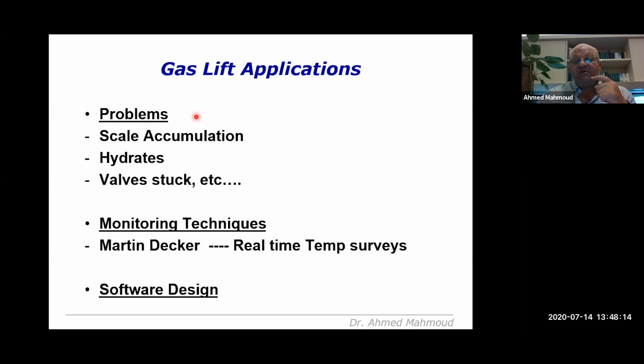And the main problem with gas lift applications is scale accumulation. And scale is very prone to accumulate. It really likes the pockets, it really likes the mandrels, it really likes the springs inside the valves, and scale will accumulate. It will cause a lot of problems. Obviously, high grades, and then both of these will affect the valves. A lot of them will be stuck open or stuck closed. But it's still not a worry, even though they are prone to problems.